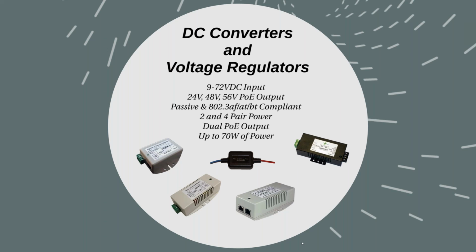So when you're trying to select the right DC converter, we just need to know what your voltage input is and what the devices you're powering need, or if you know already what voltage. But it also helps if we know what wattage, so we can make sure that we're providing the part with a high enough power, right? So whether it's just our standard 15 watts, 20 watts, or if you need 30, 50, 60 watts.